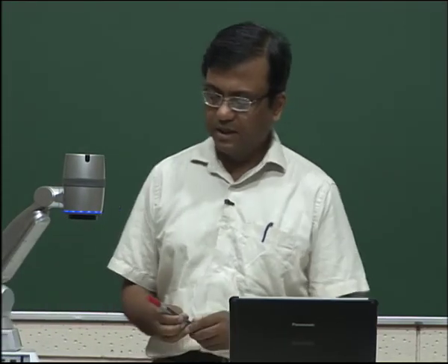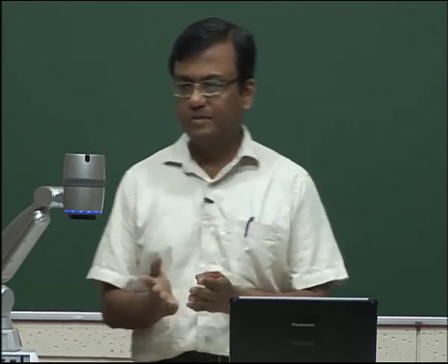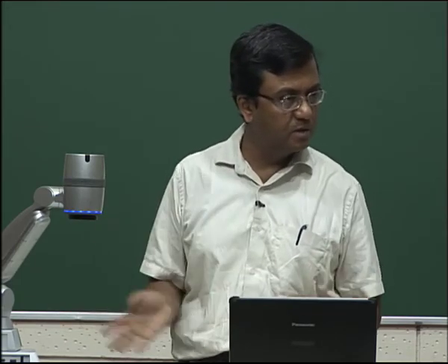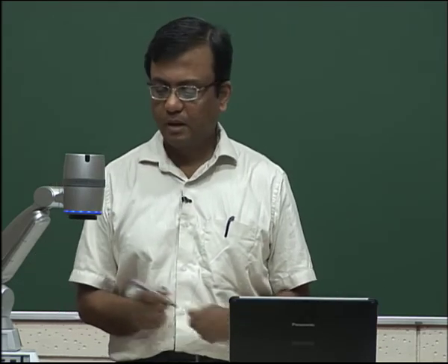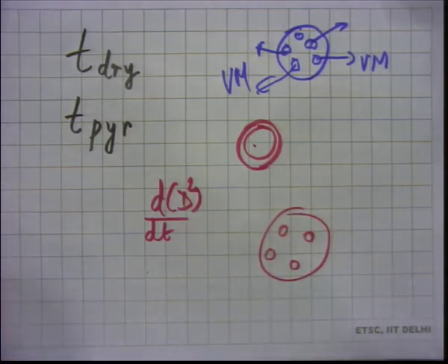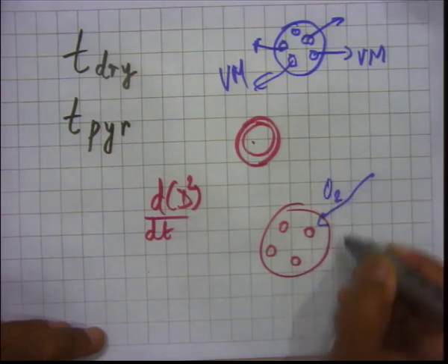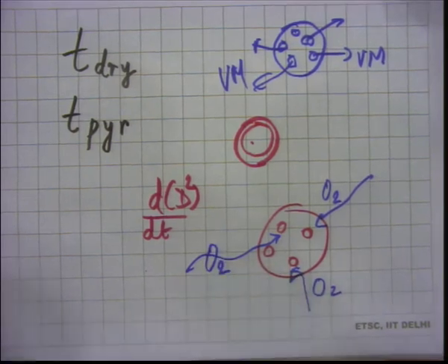And what can happen then? Once the volatile matter is gone, and that volatile matter has helped that outer flame zone, which heated the particle, now we want char oxidation, because we want to use the heating value that we have in the carbon. What is char? Char is mostly carbon, so that carbon has to burn. How will that burn? You can have oxygen coming into the particle.